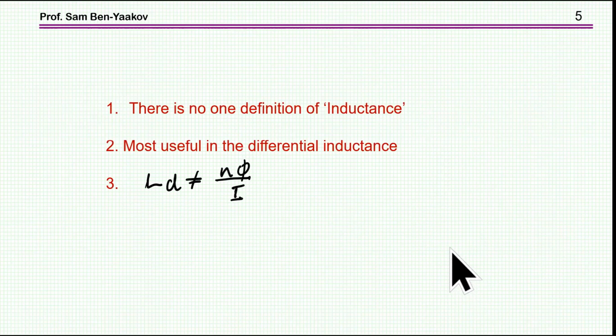So let me summarize the points that I've stressed above: there is no one definition of inductance, and the most useful inductance is in fact the differential inductance. And for that differential inductance, this definition does not hold, it's incorrect.